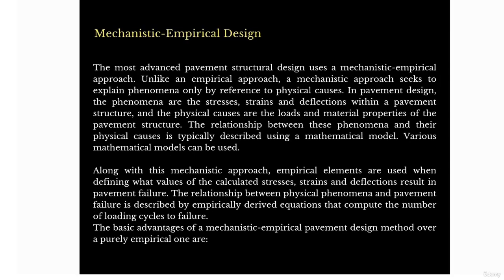So then we have the mechanistic empirical design method, right? This is the most advanced pavement structural design, which uses a mechanistic empirical approach. Unlike an empirical approach, a mechanistic approach seeks to explain the phenomenon only by reference to the physical causes. So it will look at load repetition and how it will respond to deflection under various load repetitions.